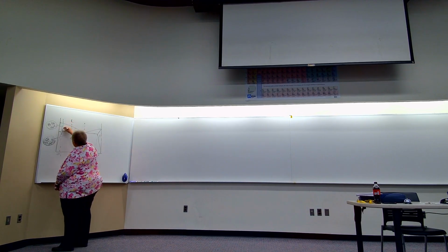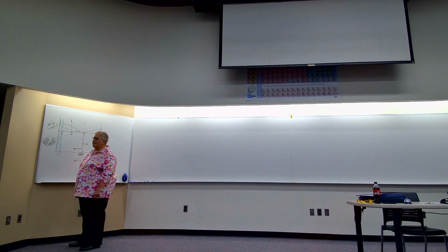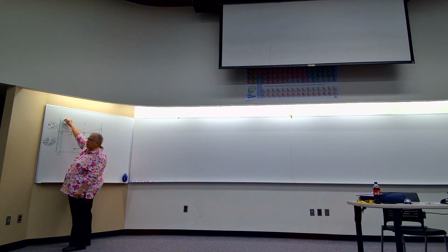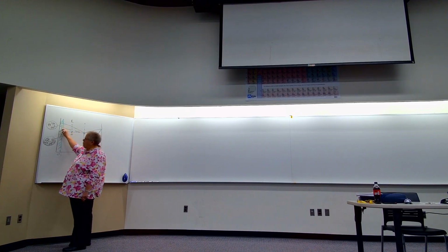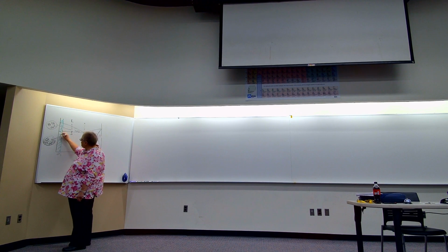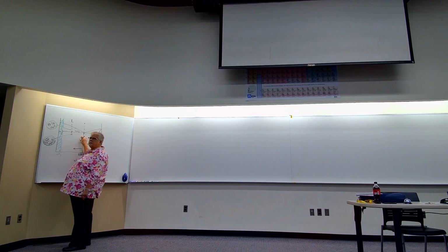The off-eutectic side, right? Any of these compositions. And what happened there? I had liquid, I cool down, I start to make alpha in the liquid until I have all alpha. Continue to cool, it's all alpha, all alpha. And now some beta is in the alpha. But that beta is not eutectic.